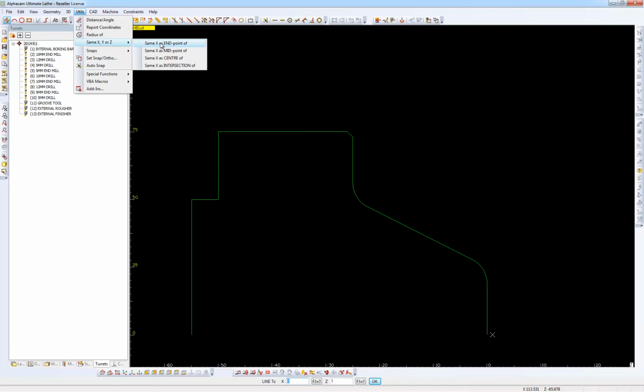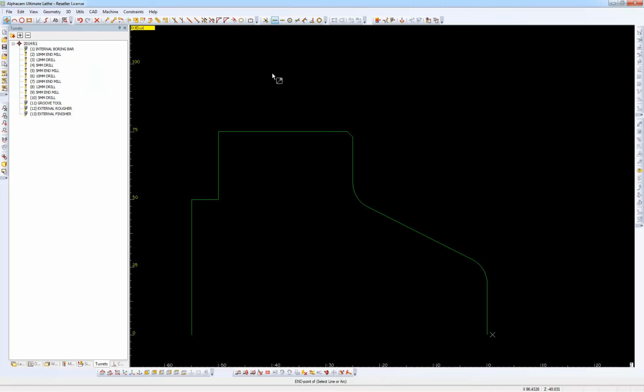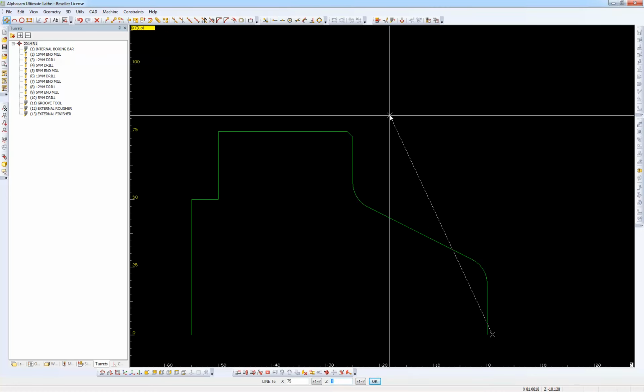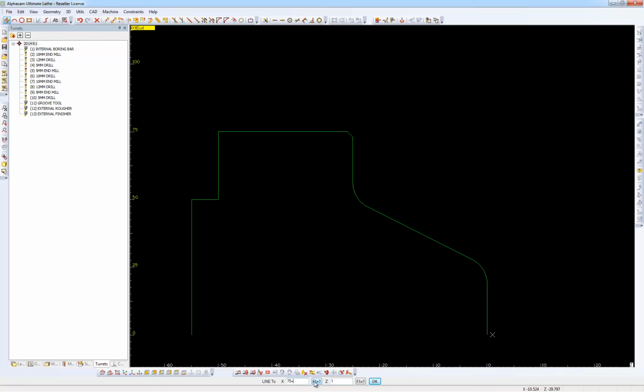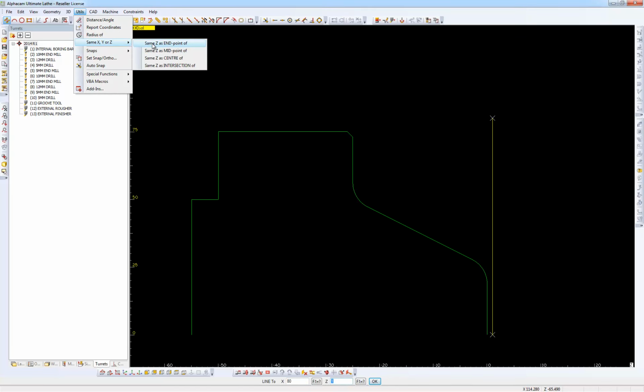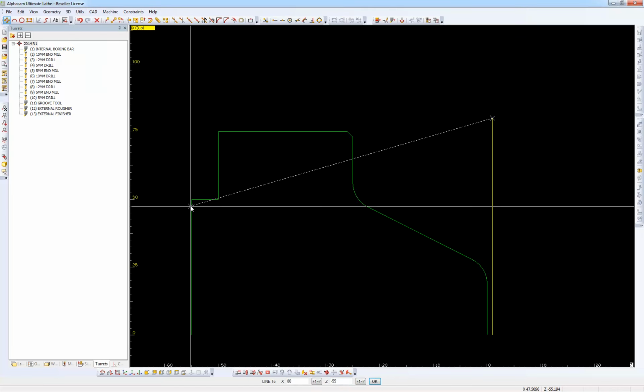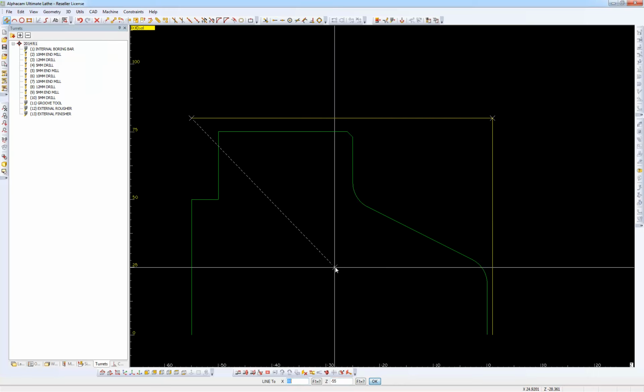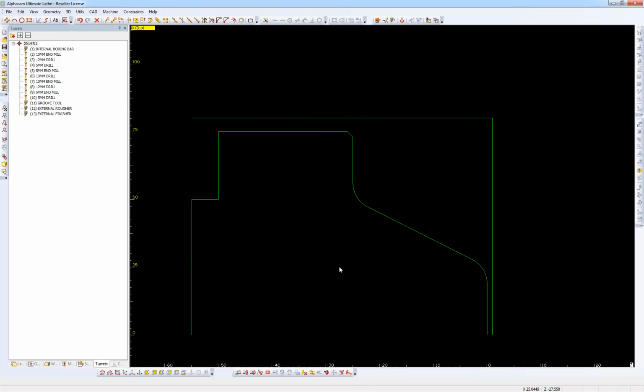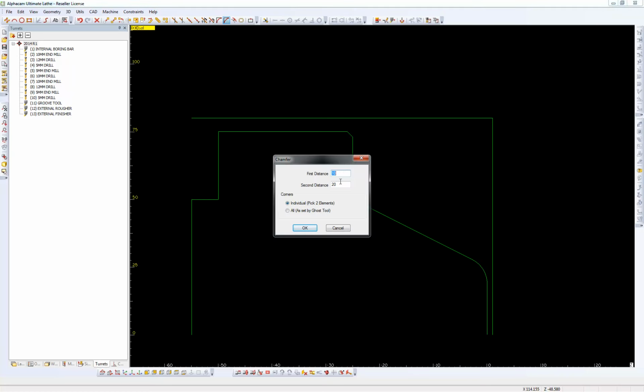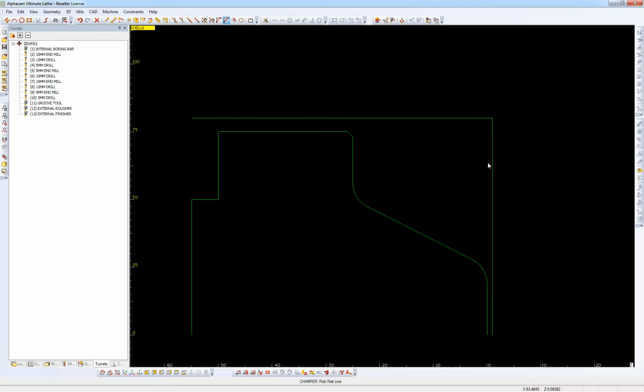So I'm going to use a tip, which is the same endpoint of here for my X, and I'm going to add some stock. And my Z is the same as the last Z. And now I'm going to do the same for the Z, so it's the same as the endpoint of there. It's okay to that. I don't want this to be a bar, I want it to be a slightly different billet shape, so I'm going to use the chamfer command by 10 to 20.